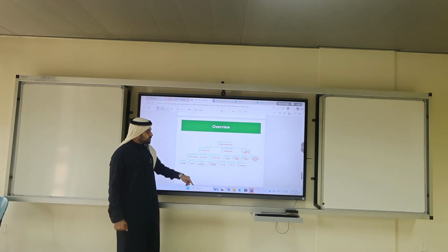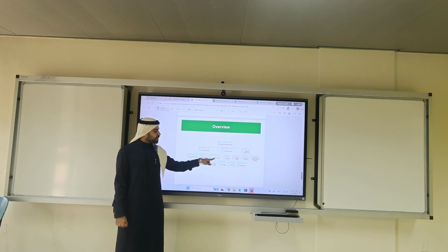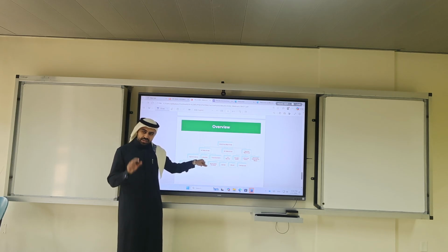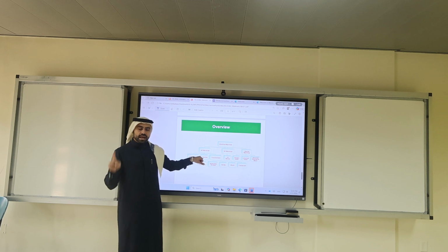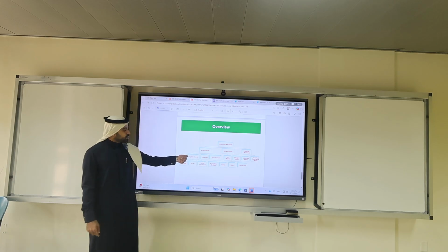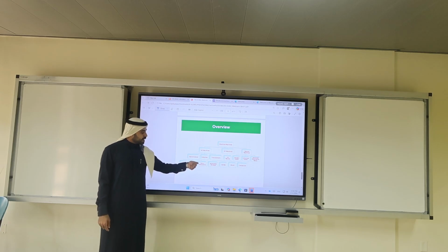So we have AC machines. Transformers are machines, but they are machines without movement. They don't rotate. That's why their efficiency is high. We have induction machines, usually three-phase induction machines, but there is a special type, the single-phase machine, where we need to have a circuit in order to operate this induction machine. We usually also have synchronous machines, permanent magnet, brushless DC, and synchronous reluctance machines.